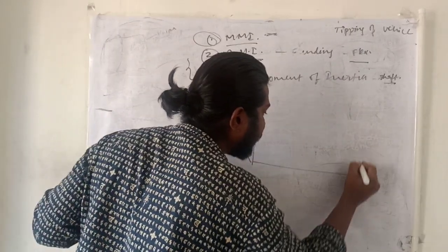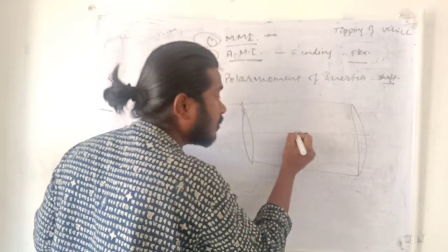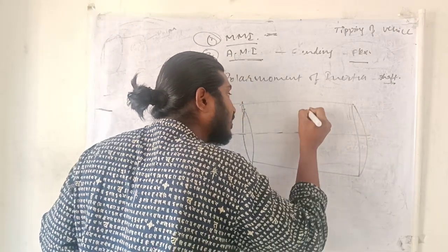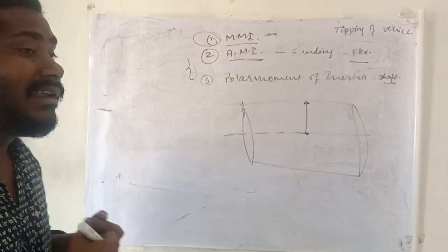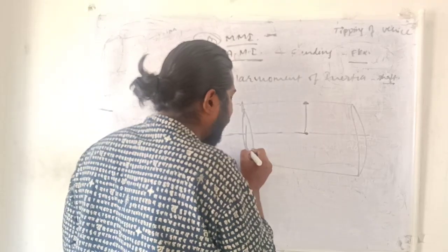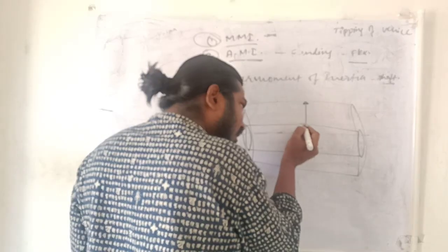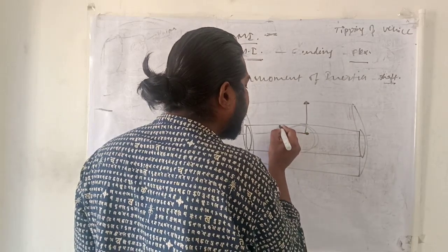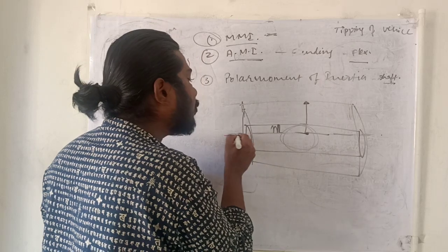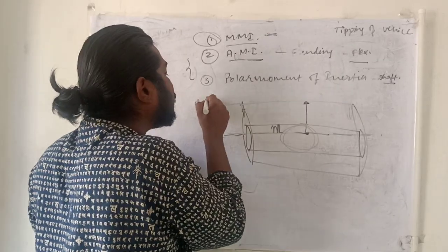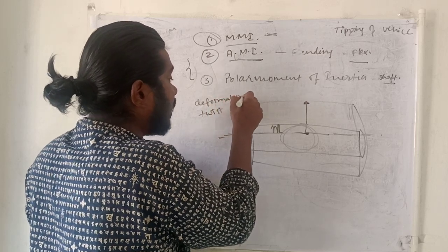the shear stresses increase from the center, from the neutral axis to the extreme fiber. The value of the shear stresses starts to increase. If you go with the analysis on any software, you can find that the inside region, or the near vicinity of the neutral axis, opposes very little to any deformation or twist.